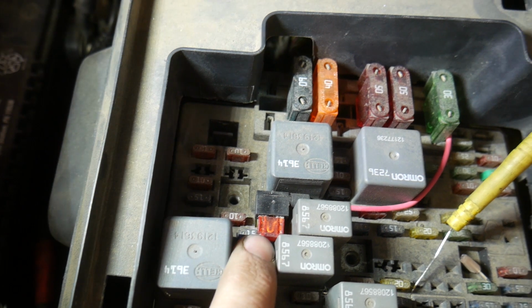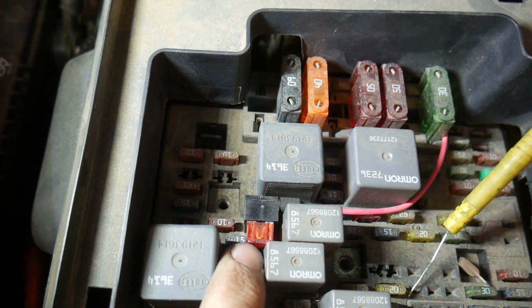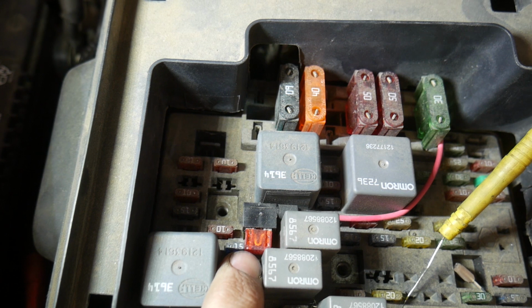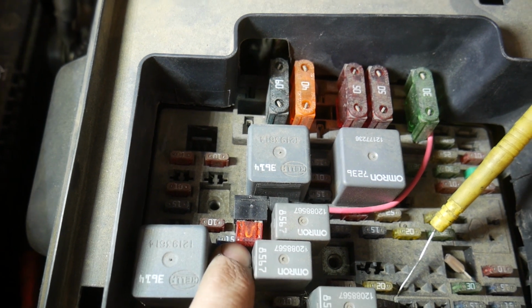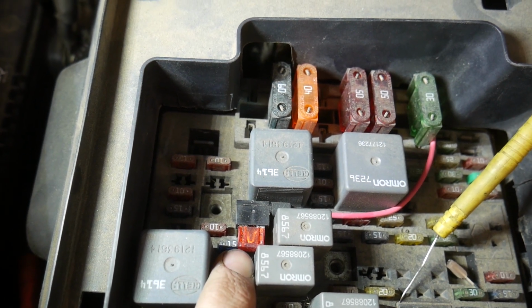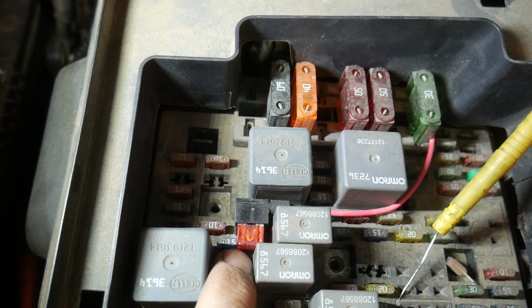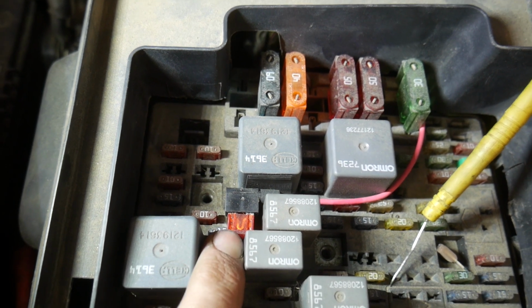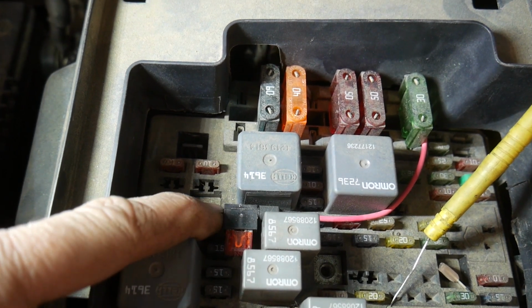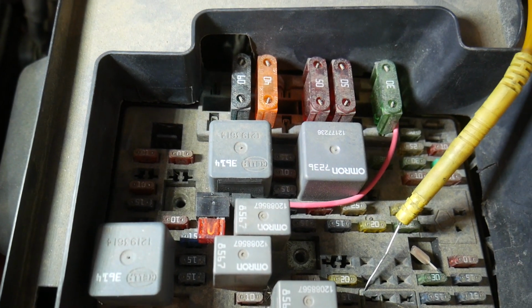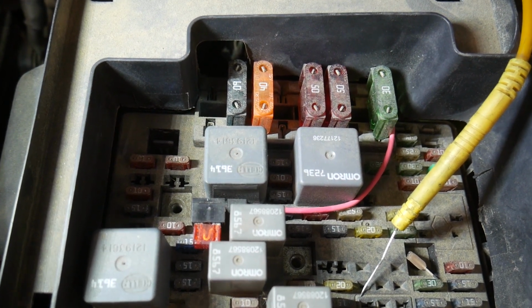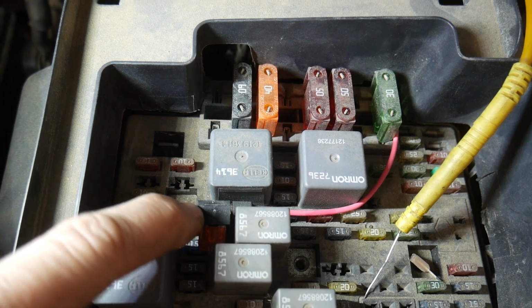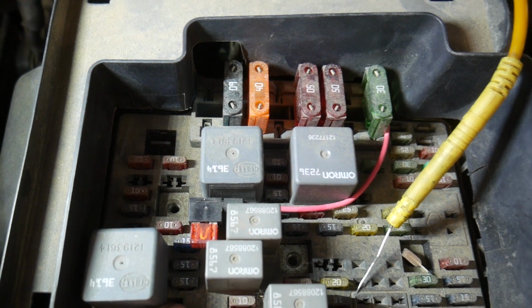So then fire up the engine and the EVAP system decides to kick on and the purge solenoid's going and the vent closes. It's going to add a couple more amps there, and it's going to be enough to pop the lower fuse and not this top fuse. So this fuse tap is in backwards. It shouldn't be tied into the PCM. And I'm going to remove that, put a regular fuse back in there, and this truck should be good to